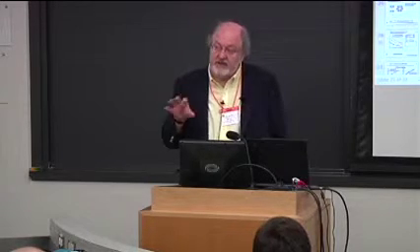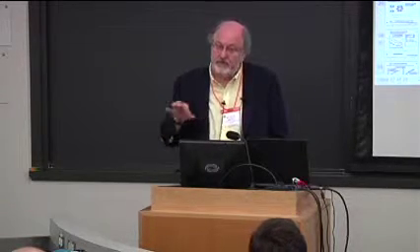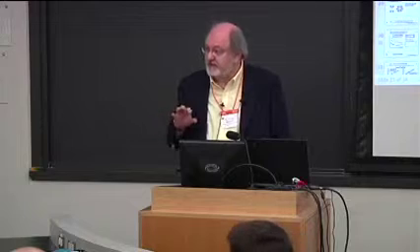I think Mario told me one of his simulations just of the breakup of the jet that I showed you was a month on, I think, 256 computers. So that's not going to be helpful if you're designing an engine. But at the end of the day, we can use his results to figure out what drop sizes and breakup lengths and things like that we can expect, and then tune our models using that data. It's kind of like the reduced mechanism issue with chemistry.